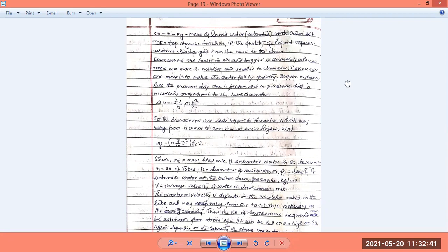So, we went through a term known as circulation ratio, or CR. It was defined as the flow rate of the saturated water in the downcomers divided by the flow rate of the steam released from the drum itself. As per our design, the drum is connected to a downcomer at the bottom of it.